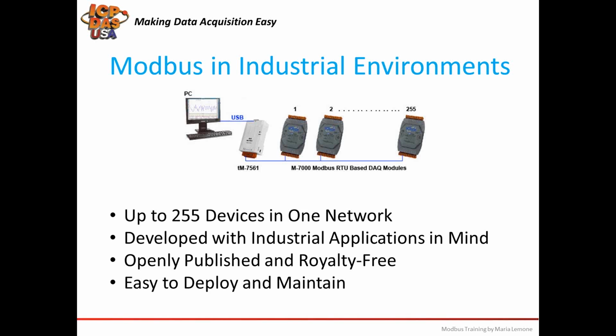Modbus applications are easy to deploy and maintain. Each Modbus device in a network is given a unique address. In serial Modbus RTU networks, only the node assigned as the master may initiate commands. In the Ethernet-based Modbus TCP networks, any device can send out a Modbus command. One master device is usually configured to send Modbus commands. A Modbus command contains the unique Modbus address of the destination device. Only the destination device will act on the command, even though others might receive it.